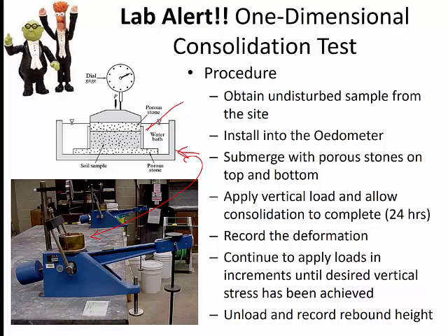And these are fairly small samples, so typically the deformation is completed within a 24-hour period. And then another load is being applied. Typically you start with a lower load and then you work your way through doubling those loads each time, and you perform a 24-hour reading process on each loading increment as this is being loaded up until a certain amount.